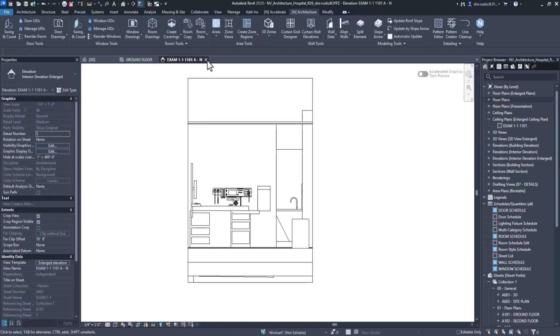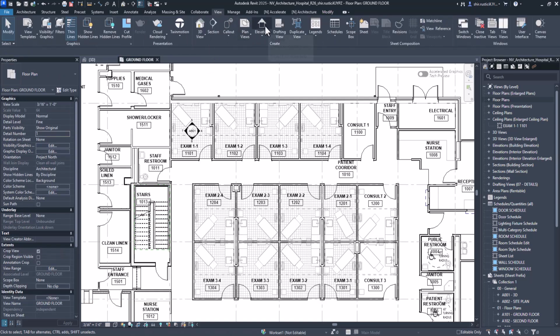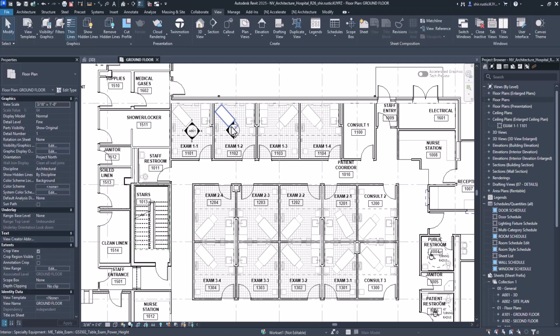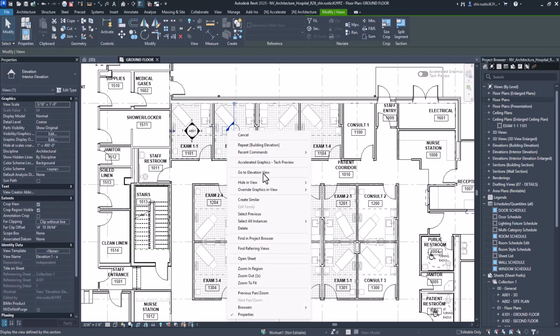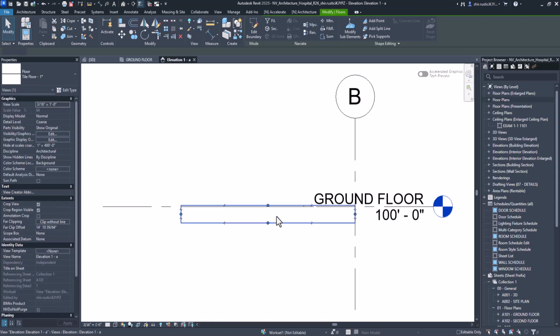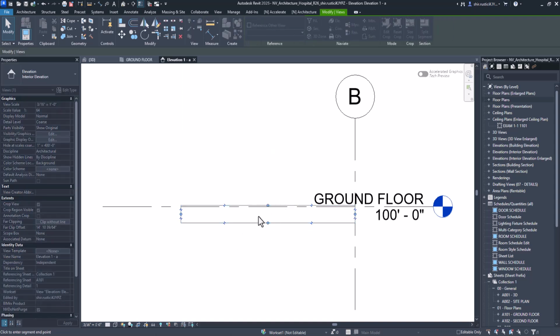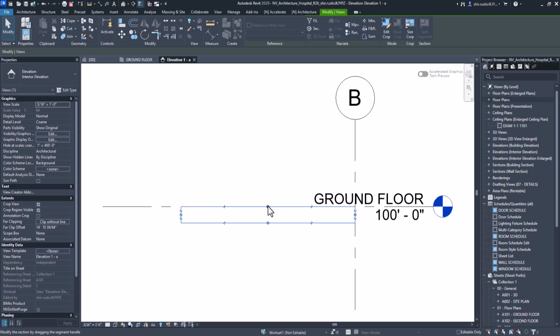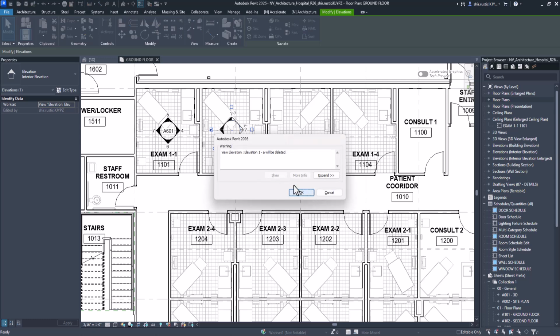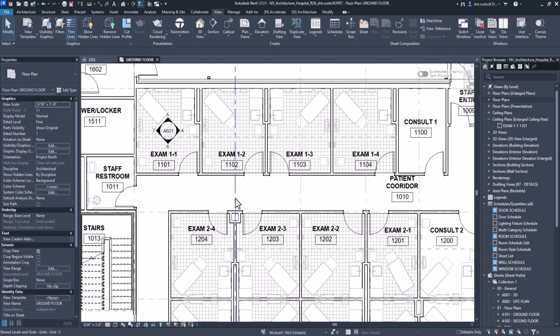slab. If we were to use out-of-the-box Revit to create an interior elevation in one of these rooms, you'll notice that we have the issue where the elevation isn't taking the proper height. It stops at the modeled finish because it's reading the room as between the structural slab and the finished floor. Now, with Naviate, we've corrected this in the room elevation feature.